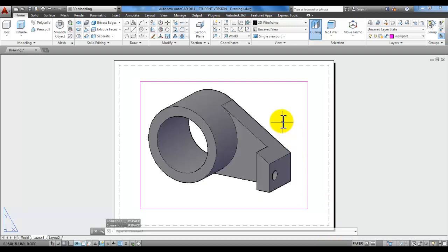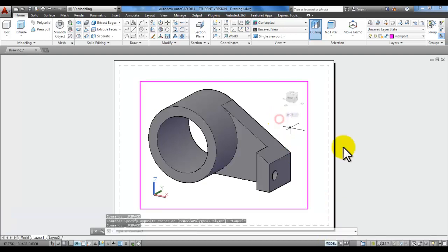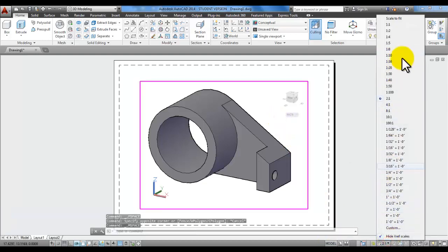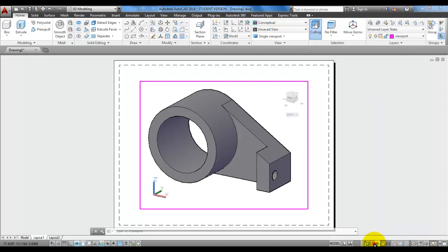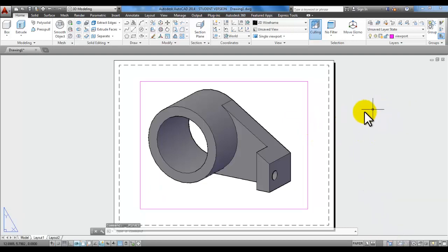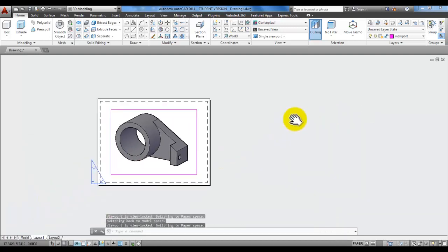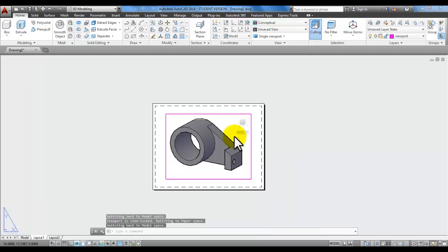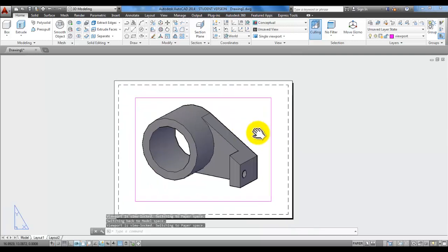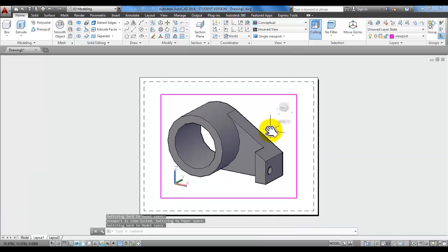And also one more thing, when you're inside the viewport and you are setting your scale, once you set your scale, there's a little lock that's next to the menu for your scales. If you lock it right there, then when you start to zoom, it kicks you out of that viewport so that your scale is set and locked.